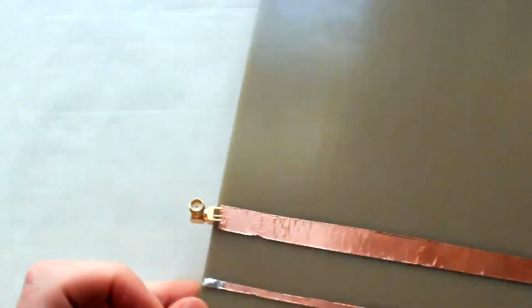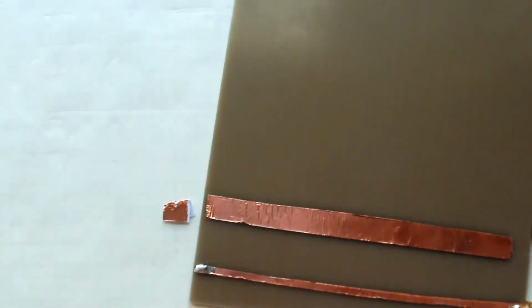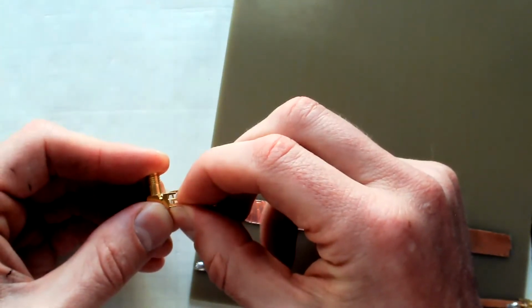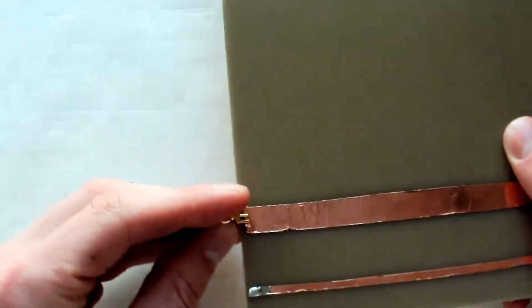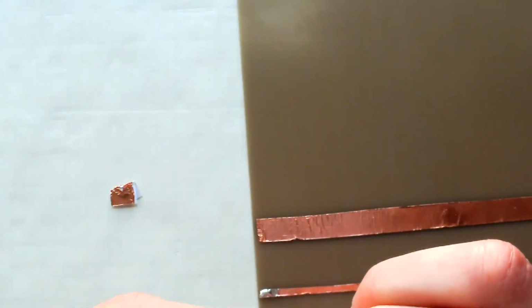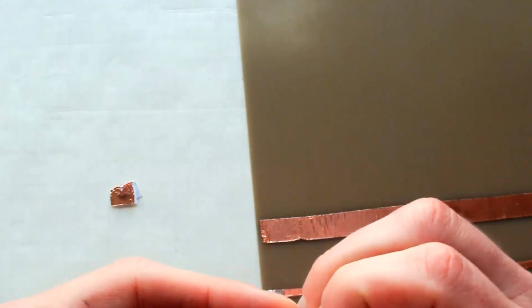I just got this guy again here. So it's making a nice contact with the copper, and that should actually register. So it doesn't have to be super great as a contact. So again, you might have to struggle with that. What I did is I just very gently bent that inner conductor down a little bit. So that gave it a nice little pinch as well to get on there. So you might have to do a little bit of trial and error there, but once you get it to work, it doesn't have to be a perfect contact to get data off of your nano VNA.